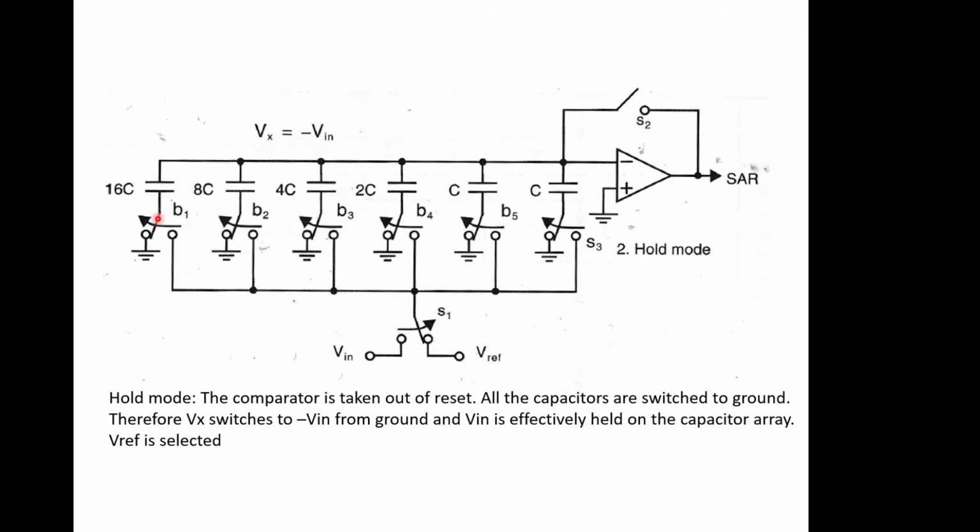So remember, they're all still holding a charge, and they've all got the same voltage across them. And now, because they all have to maintain their voltage because they're capacitors and the charge hasn't been allowed to go anywhere, we end up with this polarity switch. So it's similar to what we looked at in terms of the inductors and the switch mode power supplies, and also for the switched capacitances when we were messing about with negative supplies. So we're doing the same kind of idea there. It's got the same voltage across all these capacitors, and so this now pings down to a different voltage. So that's our sort of sample and hold.